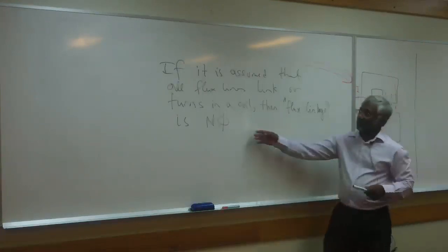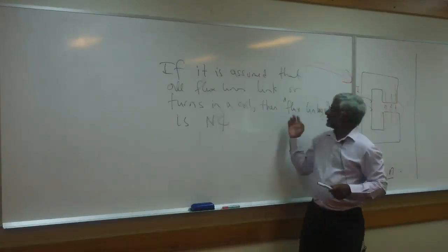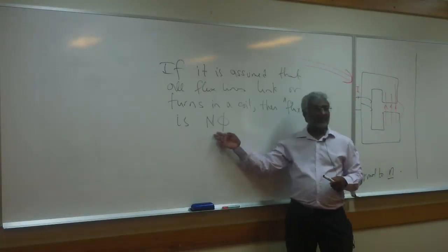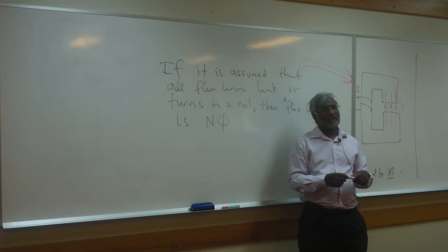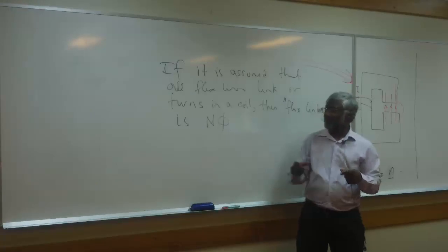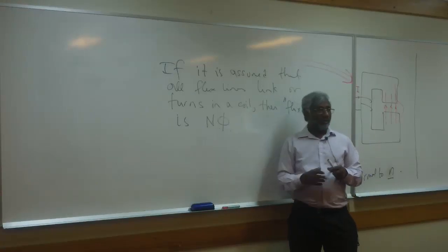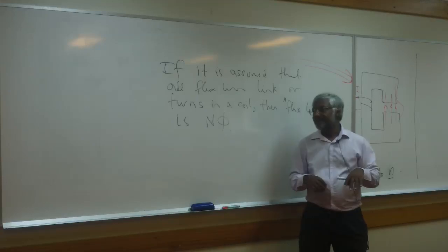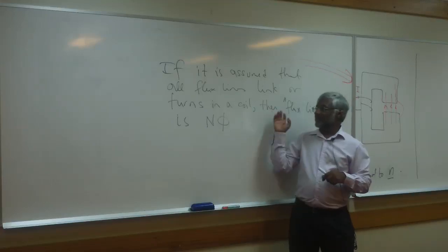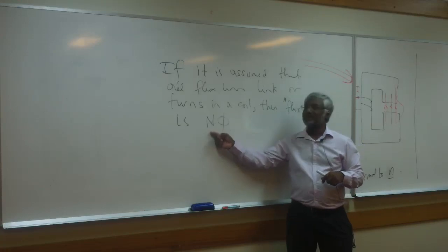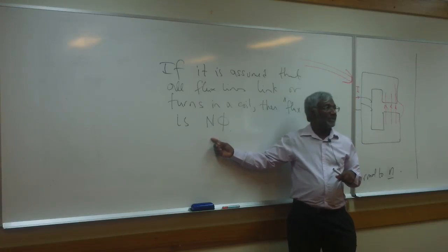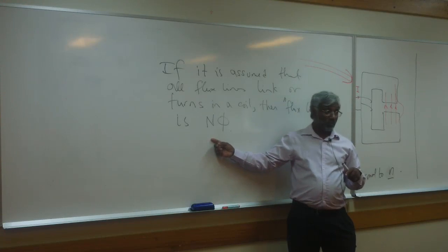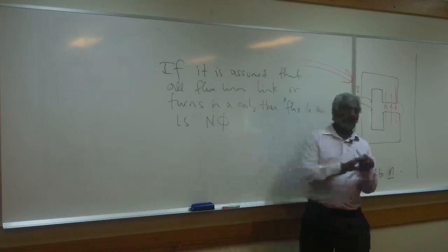people have defined that. Now, this idea of flux linkage is only true if all the flux link all the turns, which in situations that we are looking at, like in transformers, is almost true. On the other hand, if you come back to reality, then the flux linkage is actually a bit less than this, because there will be some flux that link only some of the turns and not all of them. But we are not going to worry about that today.